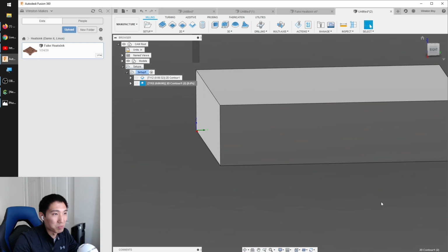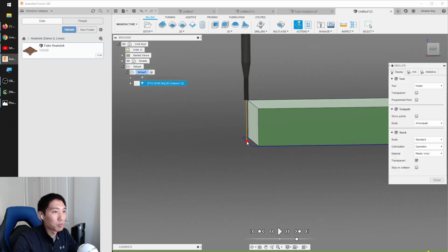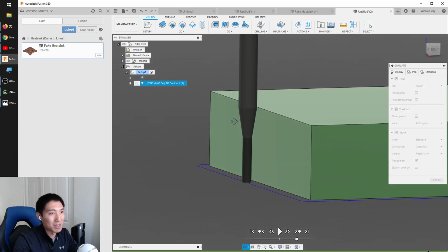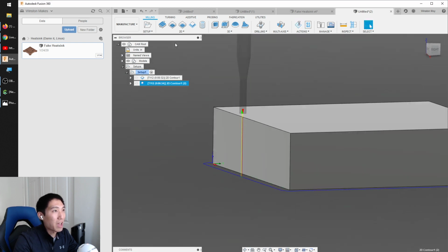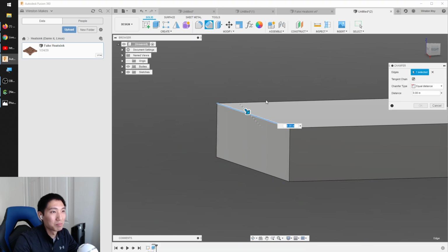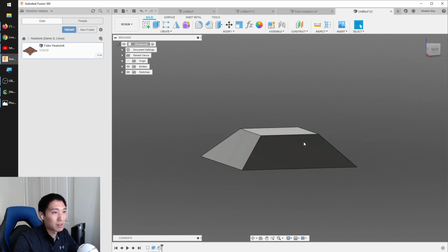But at that point, you're really losing the benefit of using an end mill like that. So when it comes down here, the shoulder would be off the wall. You can dial that in a little bit. However, if you're going to do something with a chamfered top, then you could use a 16th inch end mill and carve a really tall pyramid, because there would be no collision with the shoulder.